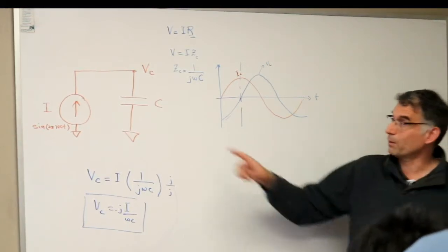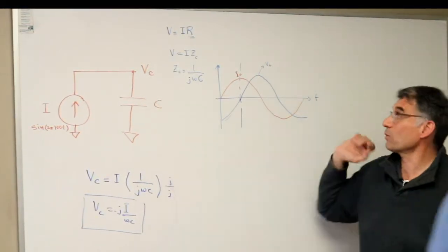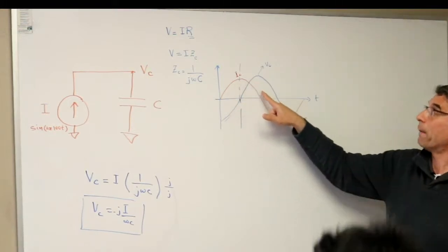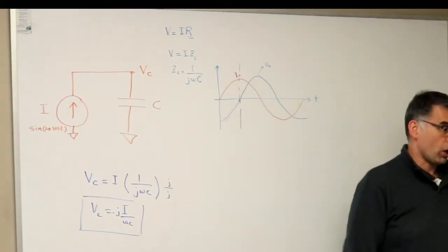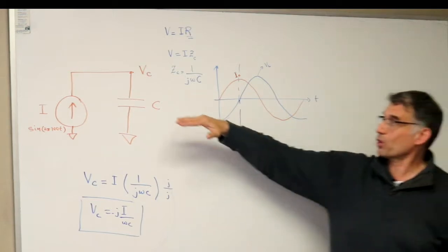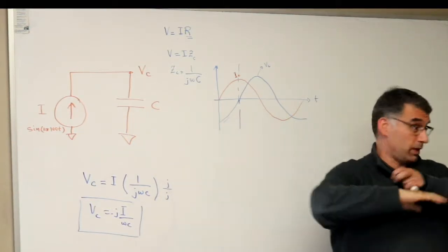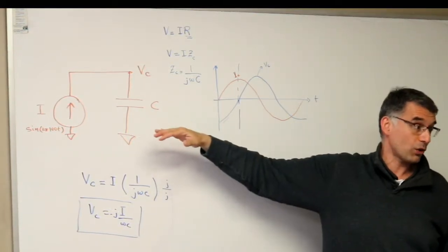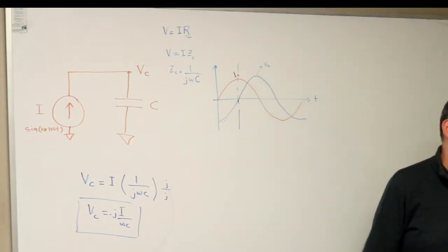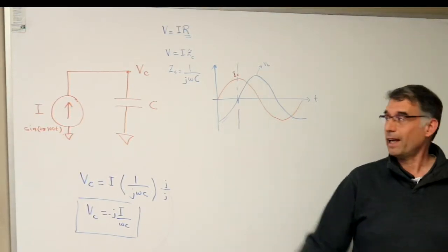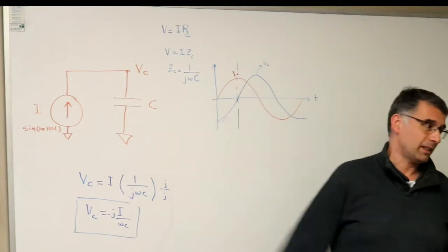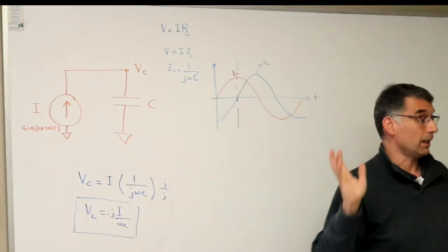The current source is the one that's pushing the charge through. So once the current source says, I'm done pushing charge, that's the maximum charge that you're going to have on the capacitor. Not the maximum charge that the capacitor can handle? No. Right, the maximum charge the capacitor can handle is based on its voltage rating.